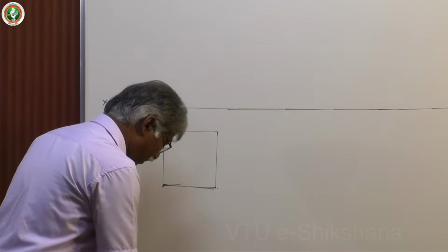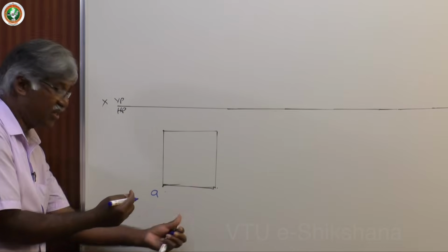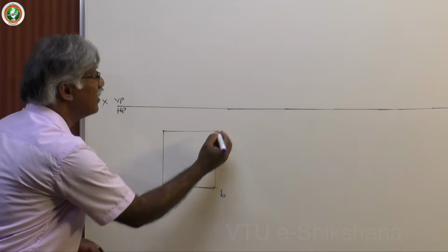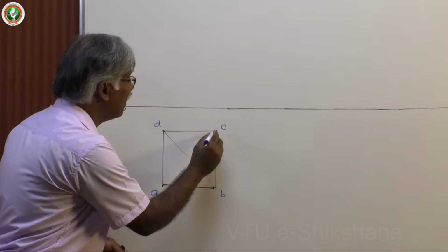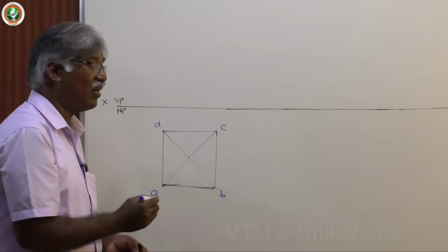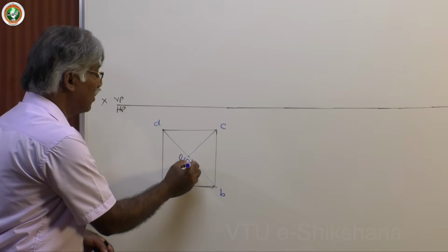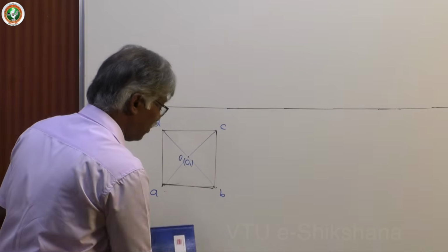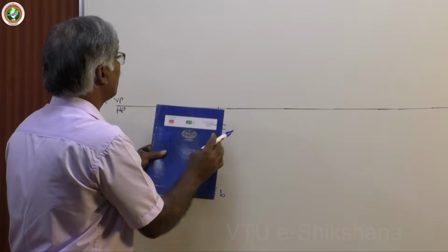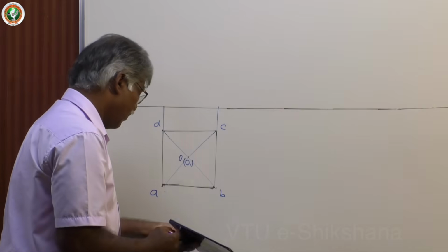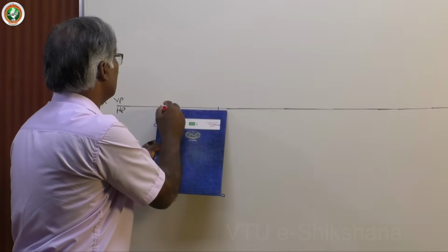Now the naming should be done. First naming should be the left extreme nearest corner A. Then this is B, C, D. Then identify the axis. This is very much necessary for solids. Top center, base center. Okay, now get the projection up to the XY line because base is on HP initially. Project it and get the final position of base on the XY line in the initial condition.